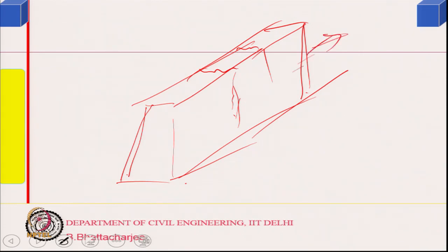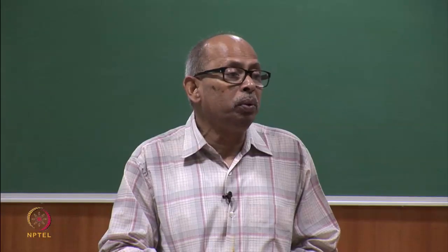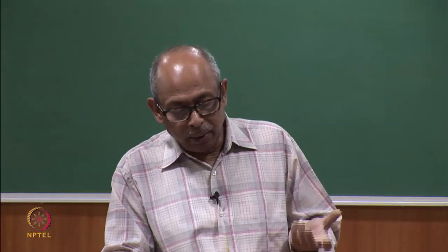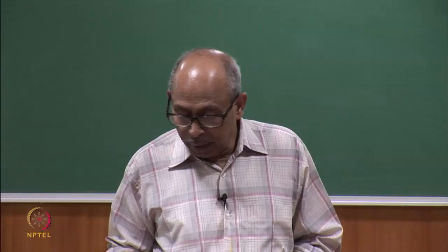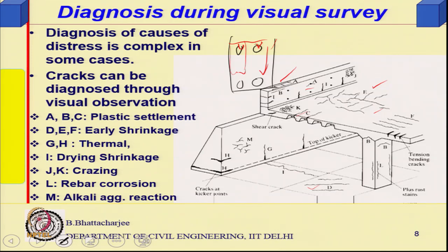So, this would like to shrink, drying shrinkage, and drying shrinkage is a function of volume to surface area. When this ratio is small, the shrinkage occurs more, and because of restrained shrinkage, this can result in cracks. There is no construction joint, long wall, there is a restraint in shrinkage, and this can show up as cracks. So, these are cracks in thin sections. You might see even cracks of this form, but if it is somewhere over the slabs, you might see something of this form, because it has dried off from the top, while inside it is still relatively moist, and relative differential shrinkage might have caused cracking. So, is the case here, and F is also D is here, E is there, F is somewhere there. So, you can see that kind of crack especially between the restraints.